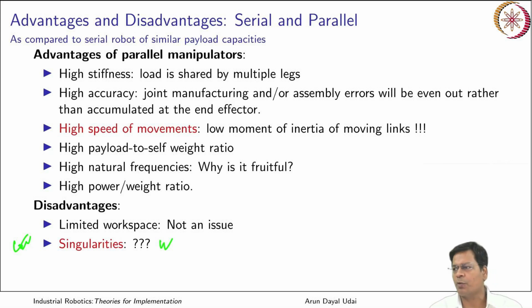As because delta robot, a kind of parallel architecture, is very, very popular in the industry, they are basically using the delta robot, and it doesn't face any singularity because it works in joint space, not in Cartesian space. It doesn't have to relate the end effector motion to its joint motion. Okay, so the Jacobian getting singular is totally absent.